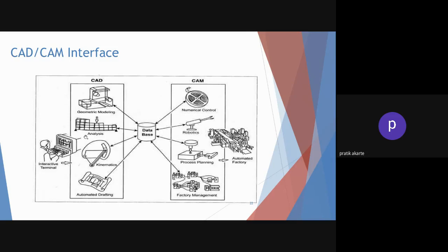Then I have performed the various machining operations onto that, like milling, then drilling, and then contouring and facing, all that stuff. And based on that operation, the application software had generated one NC program. So that NC program is your database. Now I can directly transfer that NC program to the numerical control machine or CNC, and that CNC will perform automatically, and the product will be coming out from the machine.